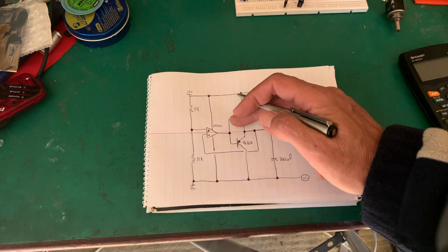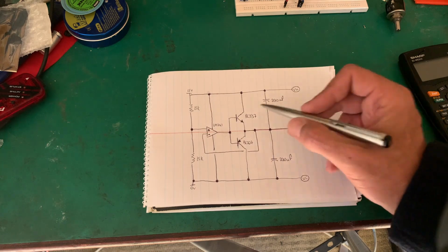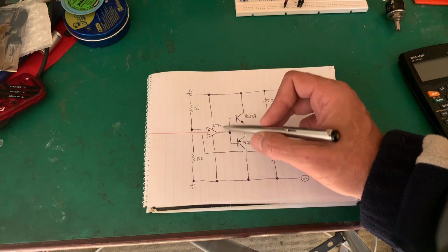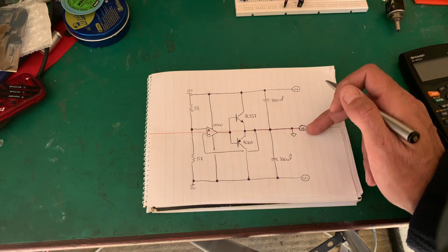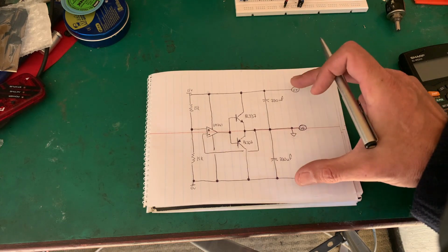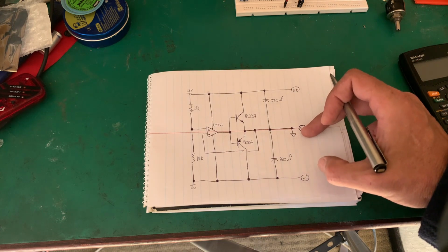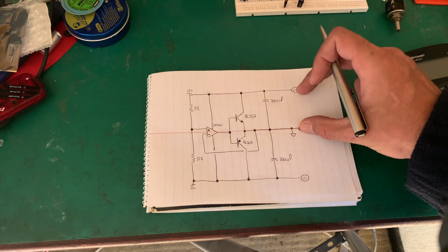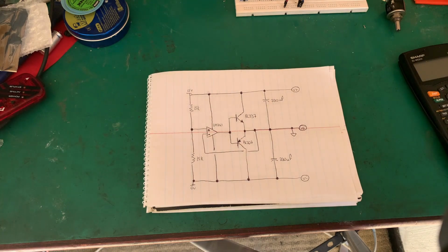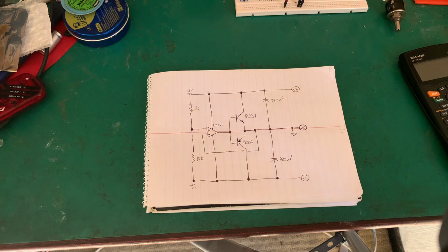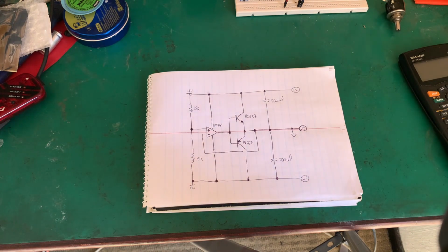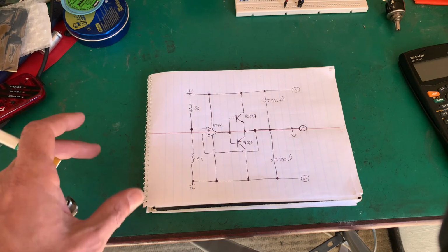We're using the op-amp to control it, and I'll show you on this oscilloscope what this output is doing to keep these two the same. So this becomes our new reference, and we've got now plus voltage, from here to here, and minus voltage, from here to here. We split it nice in the middle, and we're using our op-amp to do this. I want to show you one more circuit and then we will jump to the breadboard. Well, two more circuits.